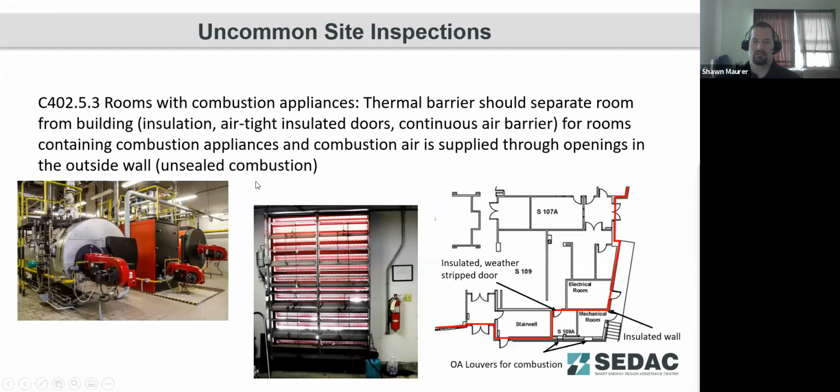So again, we're seeing this less and less now that we've got high efficiency appliances with sealed combustion. You're getting away from having a lot of these open louvers in buildings, but you do still see this if you've got a backup generator inside a building. Those diesel generators usually have open combustion and need these open louvers. So it does still crop up from time to time and is something to be aware of.